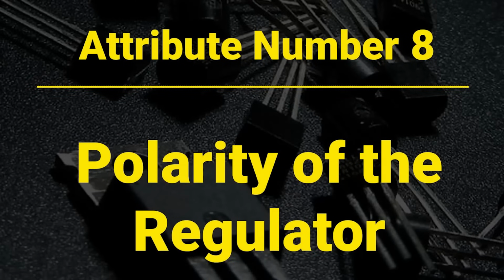Some voltage regulators have very low output current, like this LM336, which is a 2.5 volt voltage regulator, which is able to provide only 10 milliamperes of current at output. Actually, these ICs are used for making reference voltages, and because of that, in most cases, they are called reference voltage ICs. Anyway, our next topic of discussion is attribute number 8, polarity of the regulator.